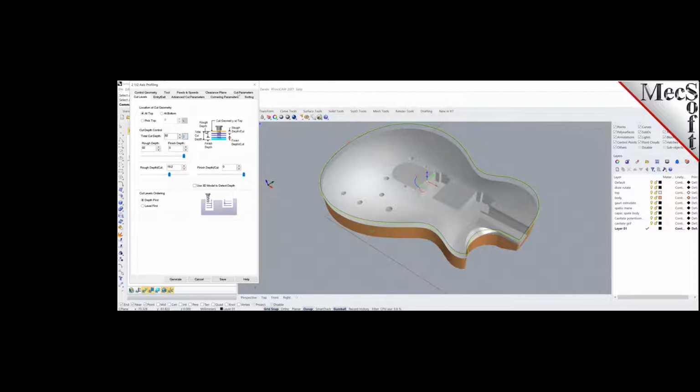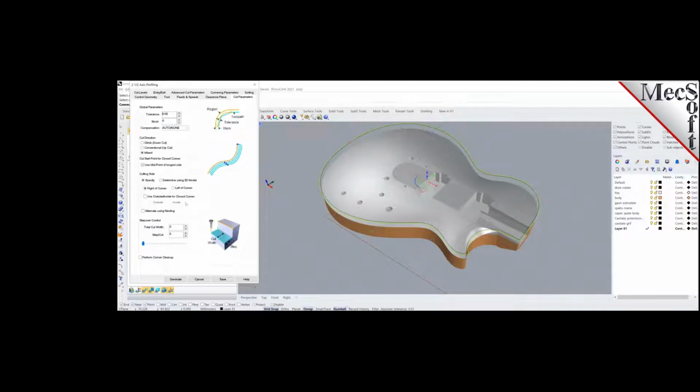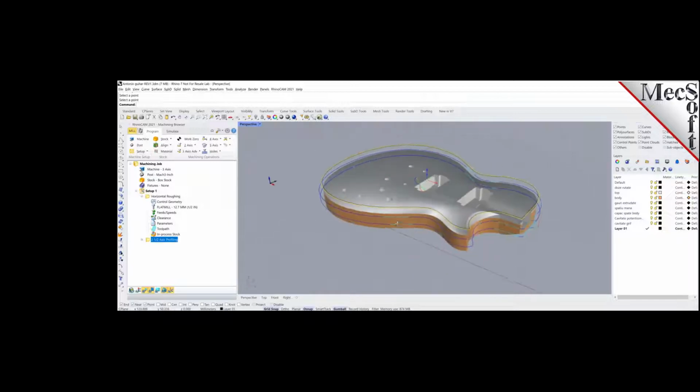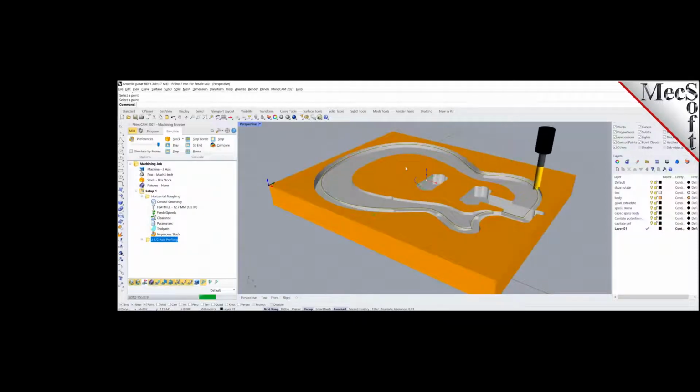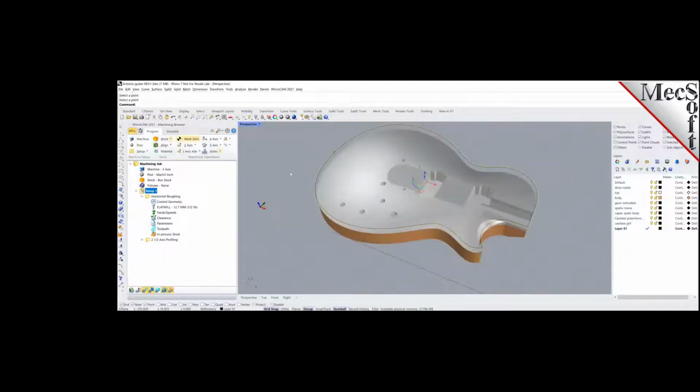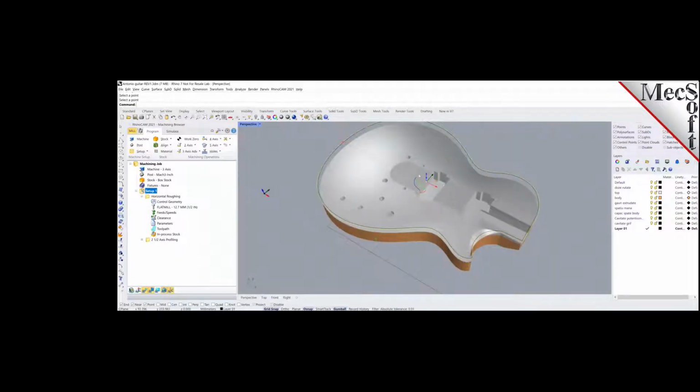Gotcha. Okay. So I'm going to use outside, and I'm going to outside cut. So there, we created that toolpath. I can run that simulation now. I'll clear the outside for you. Okay, and then last but not least, I'll just do a surface finish on the top and probably avoid these regions in the middle, so I don't want the cutter to come in. I'll turn off the gumball.